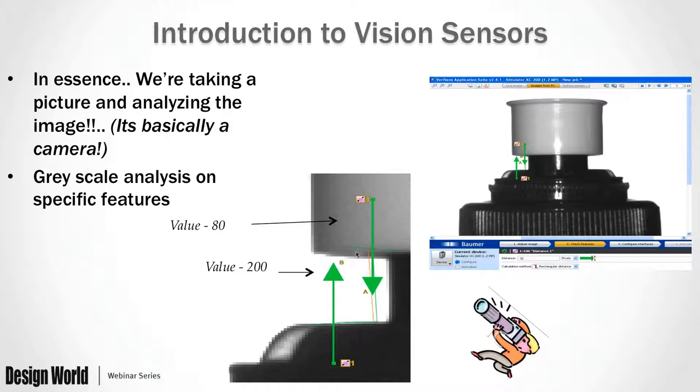So what we're doing is using software and some algorithms that detect that edge. It's looking for that specific transition from the bright to the dark, and doing the same thing down here. So we drew two line tools, soft tools if you will, taking a cursor and dragging those across. It can help us find that specific transition.